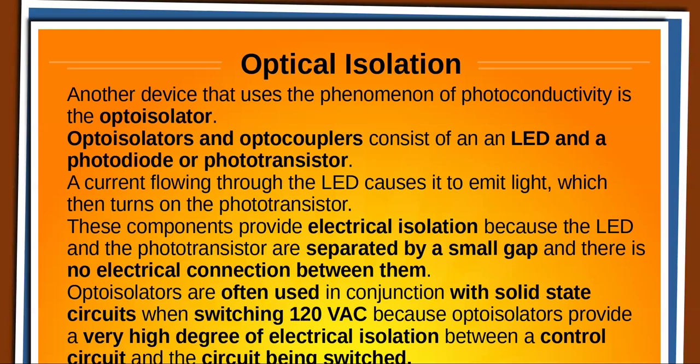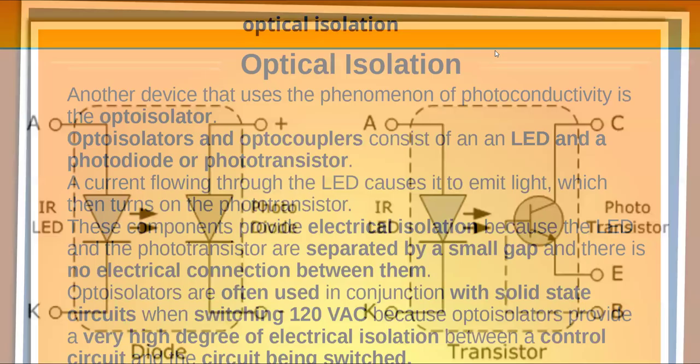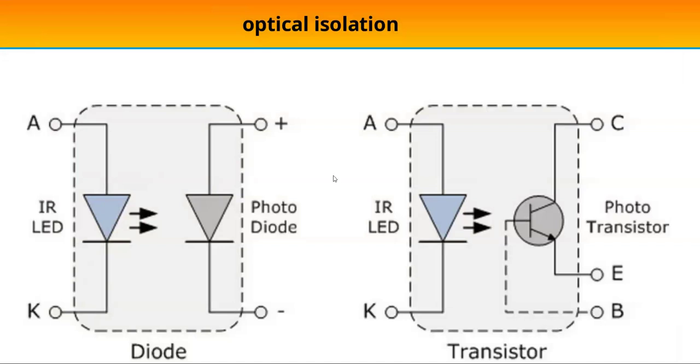They have thyristors or SCRs in them. Typical circuit for the diode isolator, where it's just a photodiode so that the LED can illuminate it, or the phototransistor version, where it kind of acts like the diode, except the current from collector to emitter is proportional to the amount of light. So instead of a switch, you can actually use it as an amplifier or controlled current device, where the diode is just on or off.